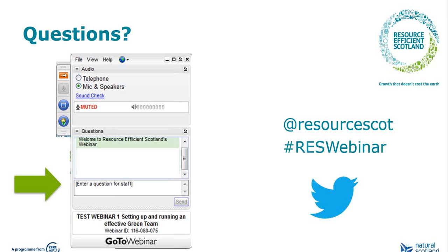So one option would be to look at the type of detector. PIR in this case you said, so you could possibly look at a microwave detector, and that would have a wider view of a wider area in the bathroom. That might sort the problem. It might be as simple as just adjusting it to have a longer time set so that people are in there slightly longer with the lights on, and yeah, it should be possible to make that work.